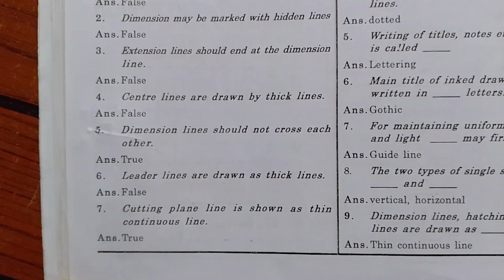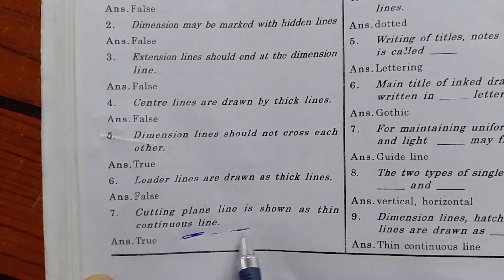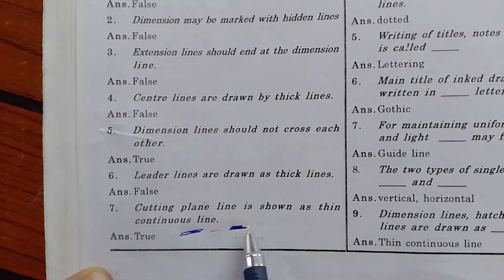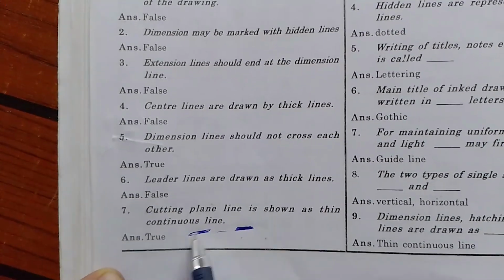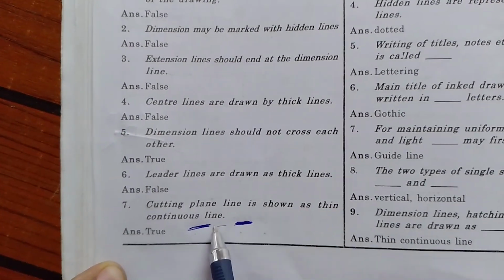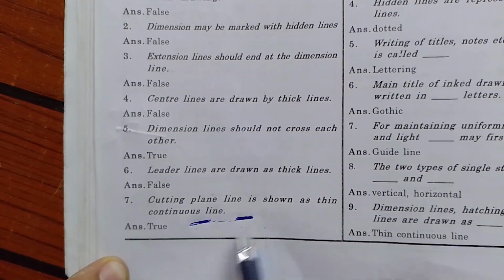It is true. Thick, thin, thick, thick, thin, thick. Cutting plane lines. Yes, cutting plane lines, to show the cut surface, it is thick, thin continuous line in between and thick at the edges. Thick at the edges. Okay, this is the convention of this line.